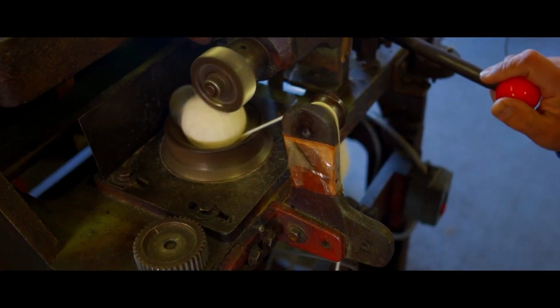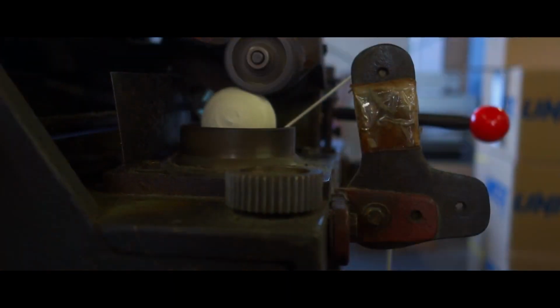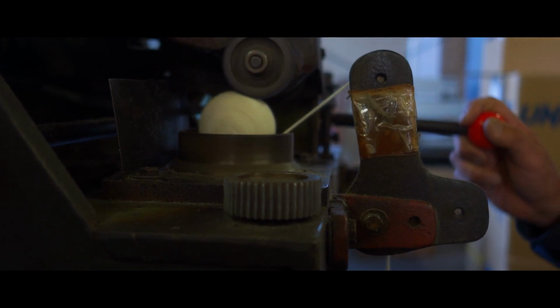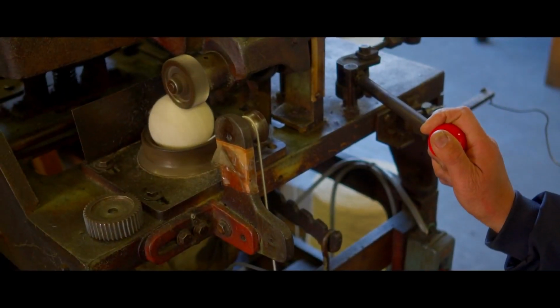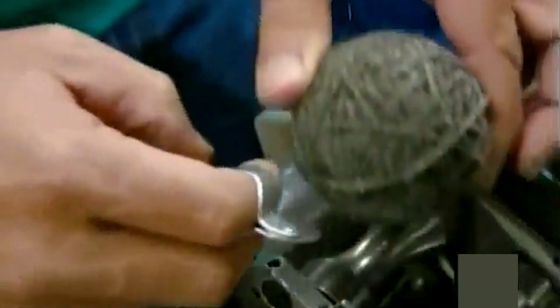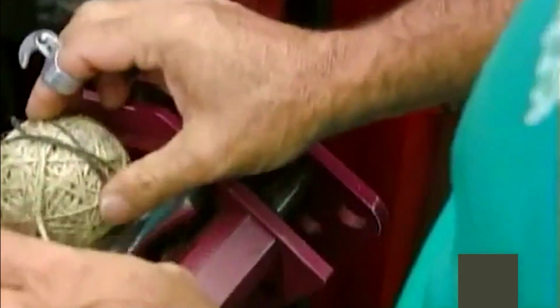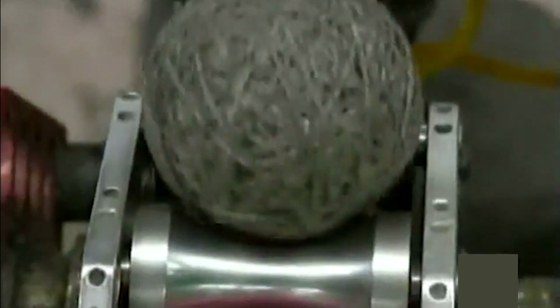Winding fabric. Wool yarn, stored under controlled conditions, is wound around the pill by computerized machines that maintain high tension to eliminate soft spots and create a uniform surface. The wool yarn is wound in three layers. The first layer consists of 121 yards, 110.6 meters, of 4-ply gray yarn. The second layer has 45 yards, 41.13 meters, of 3-ply white yarn, and the third layer comprises 53 yards, 48.44 meters, of 3-ply gray yarn.